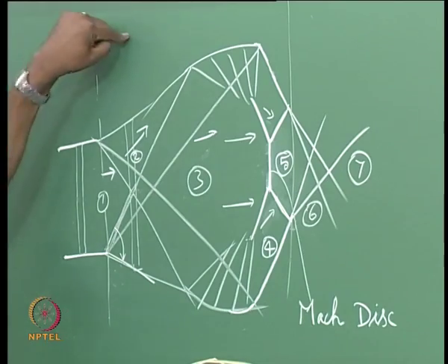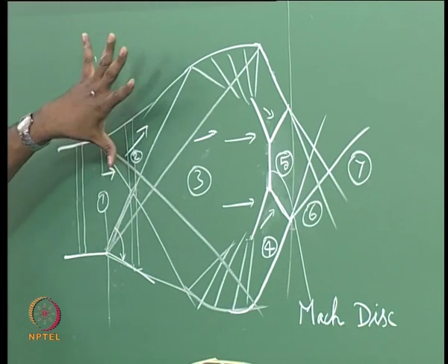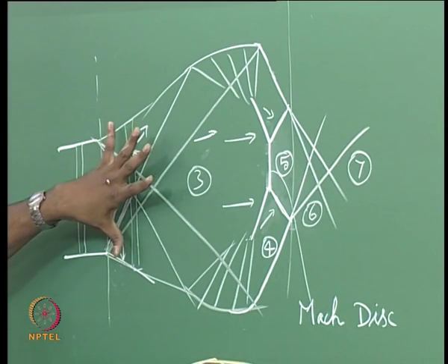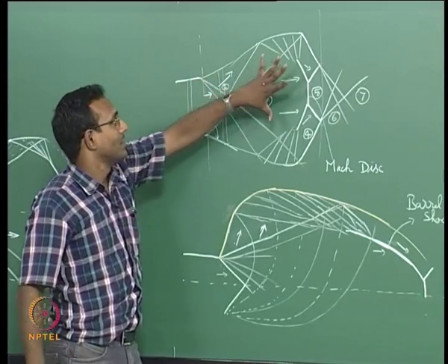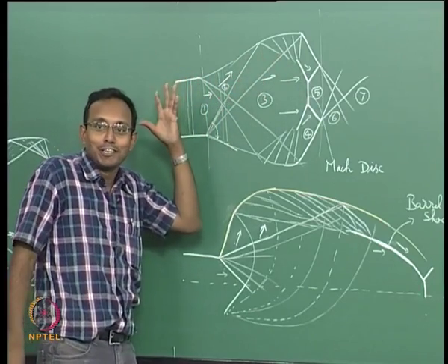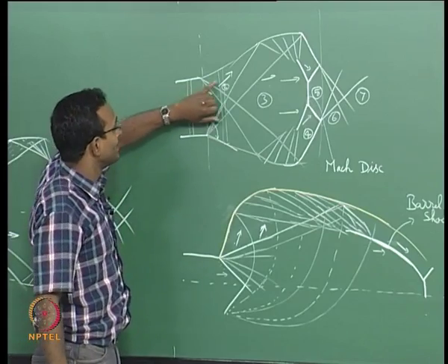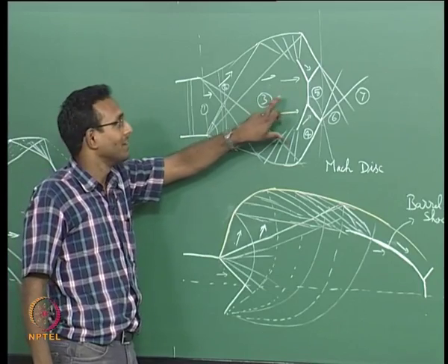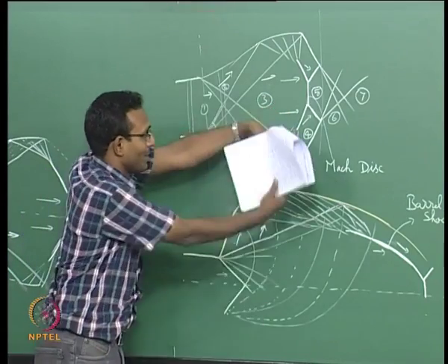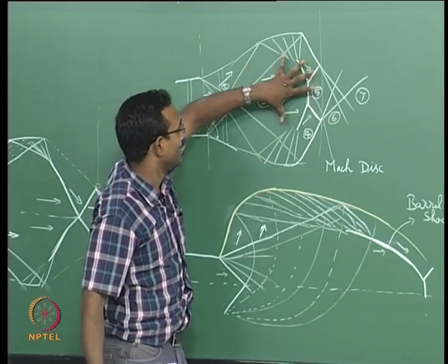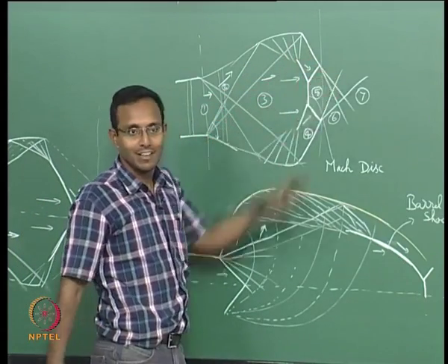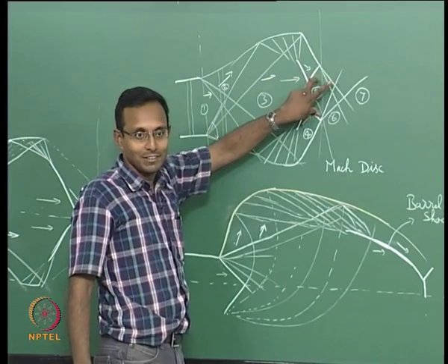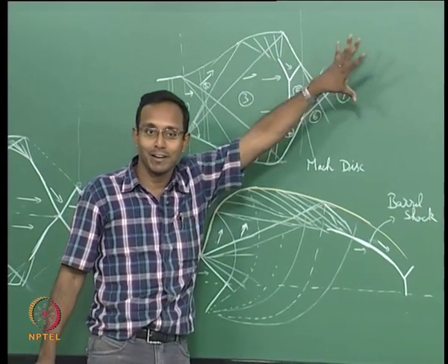Why? Because the pressure outside is much lower. It is trying to occupy all the volume there, because there is nobody occupying it. It is much lesser pressure. It is expanding and occupying the space. So it is going up. And in the process, it has inertia. If you think about it, it keeps on increasing so much that the pressure at the center drops. When this happens, then they want to implode, come back in. That is this process. It is coming back in and decreasing in size, and again it went past due to inertia, overshot, and it became very high pressure, and then it is again expanding and contracting, expanding and contracting.